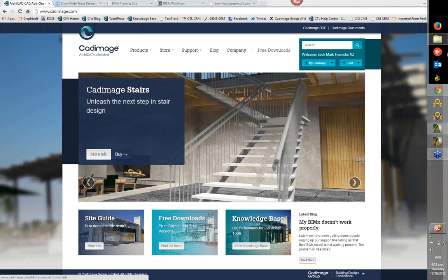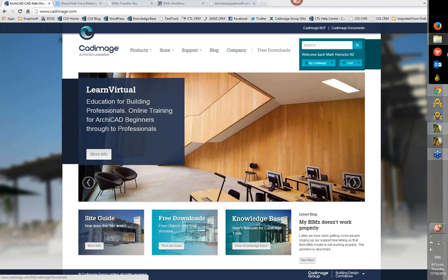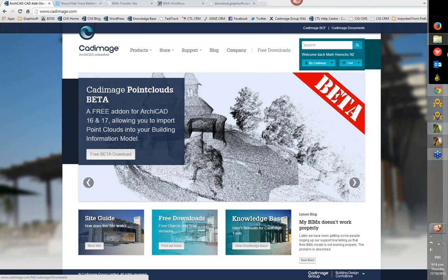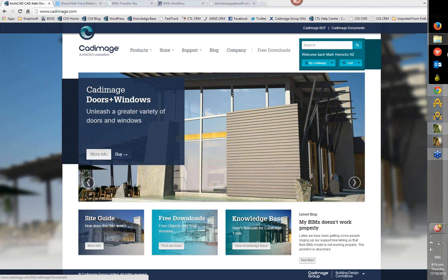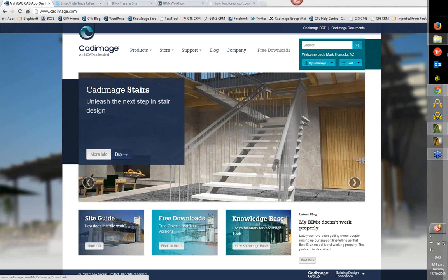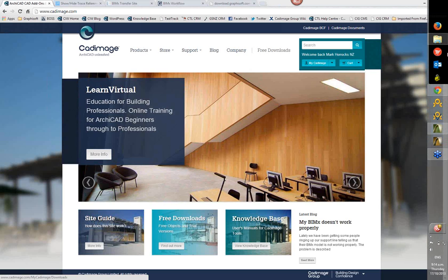If you do want extra help on that, go to the ArchiCAD 17 Help pull-down menu, go to the ArchiCAD 17 Reference Guide, and in there's a migration section which gives you comprehensive details on how to migrate from whatever version you're coming from. So that's migration there. If you were lucky enough to own EcoDesigner back in the day, migrating those files through to 17 simply works.